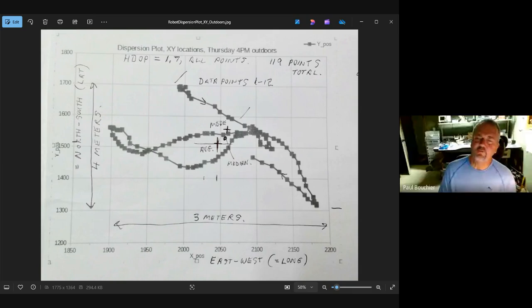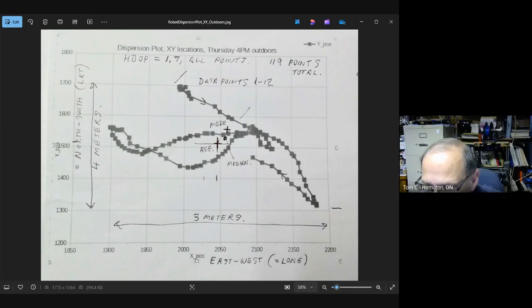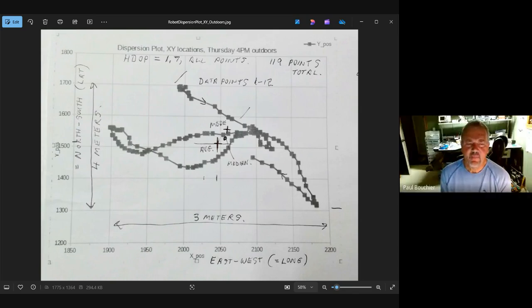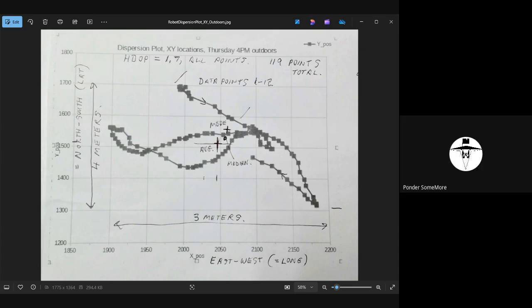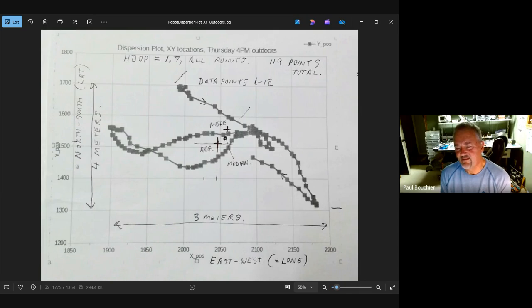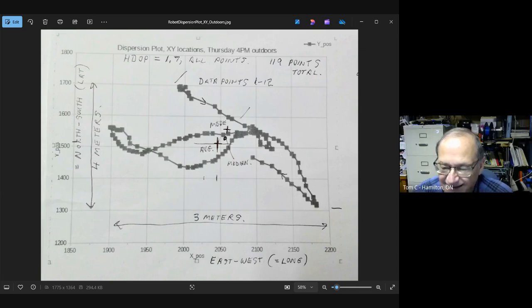Well, before you move on though, something on the ground plane. I didn't know or think that ground planes were that important for just regular GPS. They're absolutely crucial. But Paul, read the u-blox white paper on ground plane. Okay. It's an eye-opener, I'll tell you. Really? They will always help. Oh, because you don't have one in a cell phone, right? Which means they don't work very well.